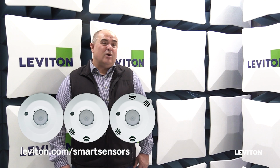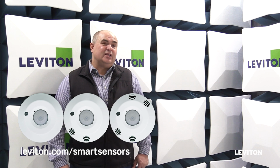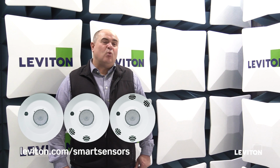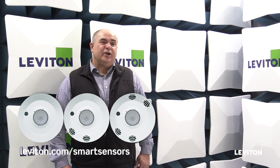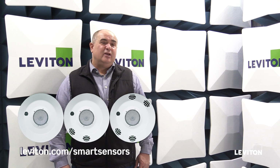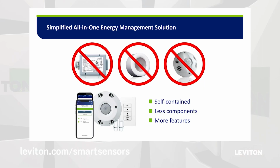How about the photocell? Well, we will have daylight harvesting in these larger areas. The general lighting wattage within the given daylighting zones will be above the trigger requirement for daylight harvesting. And then also the sensor technology, be it passive infrared or multi-tech, needs to be included. So what we have here now is a completely self-contained system with obviously less components but